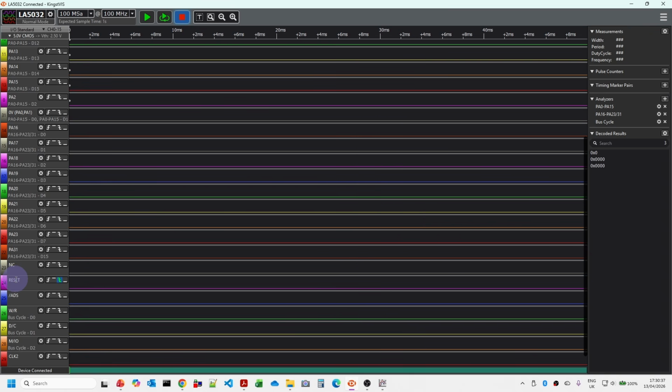And what we'd expect is to see that the no operation codes would be read from the data bus, and that basically you would cycle through all the addresses. And in the 8088, in fact, what you'd see is when it got to the end of the 1 megabyte address space, so it got to FFFF, then it would actually go all the way back to 0, start from 0 and count all the way up again until it overflowed again. So that's what the 8088 does, and we're going to expect that to happen with the 386.